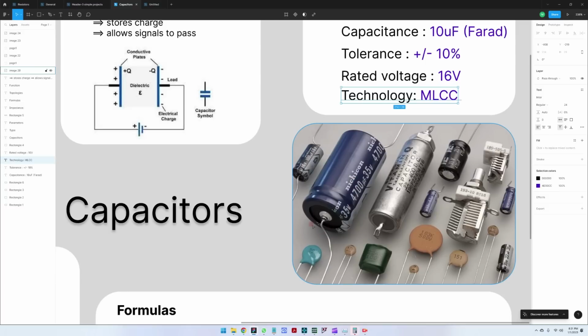So here you can connect voltage, and here this should go to ground. And same here, this is a 16 volts 100 microfarad capacitor. The arrow is pointing downwards. This means that this pin here is the negative pin, and this is the positive pin.